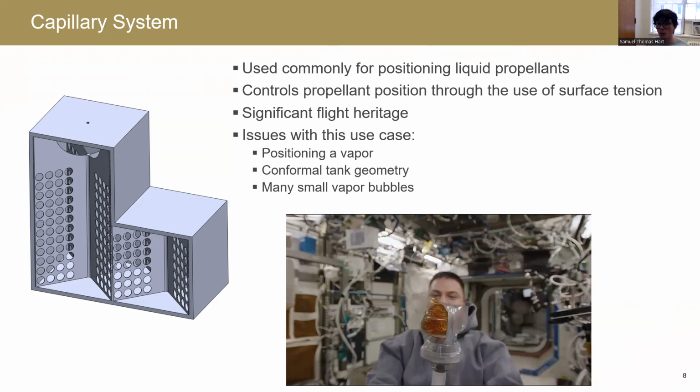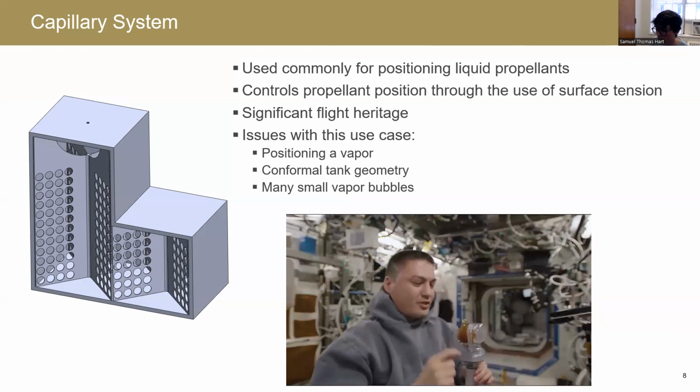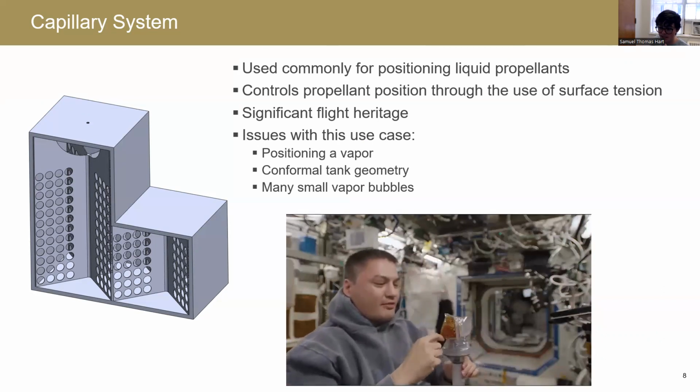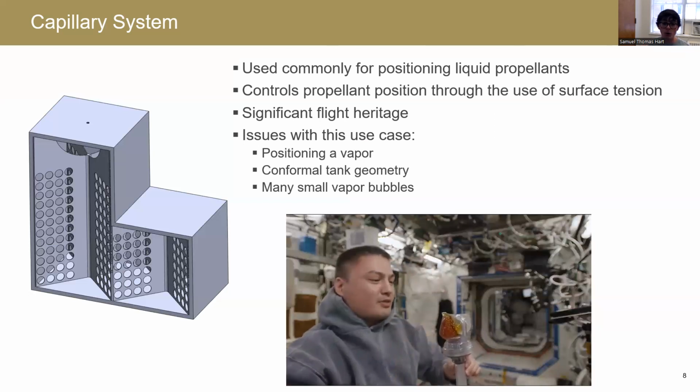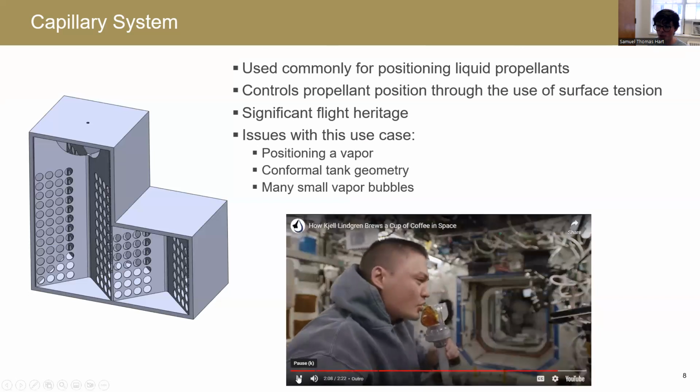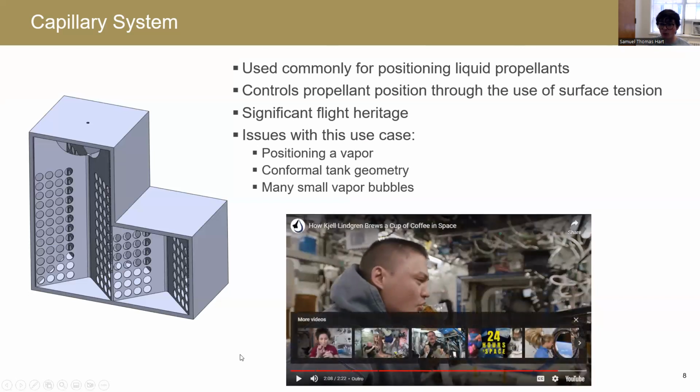The capillary forces only work if the bubble is touching a wall. And so you can see here, even now the liquid has essentially stopped moving, any small bubbles still remain behind. Now, the same thing is the reason that our capillary device will not work. If we did want it to work, we need to make sure that there were fins in our propellant management device so close together that no bubble could exist without touching a fin.